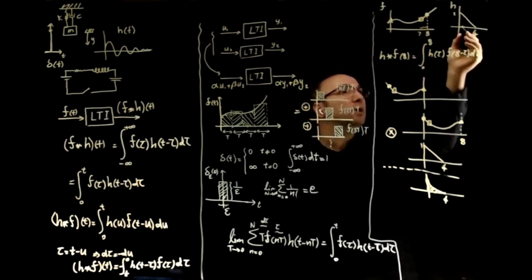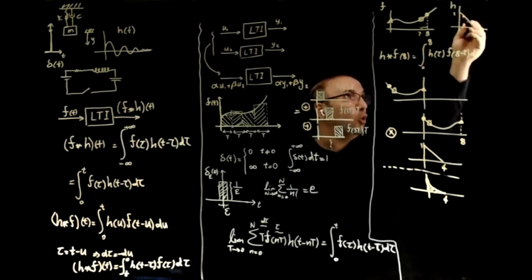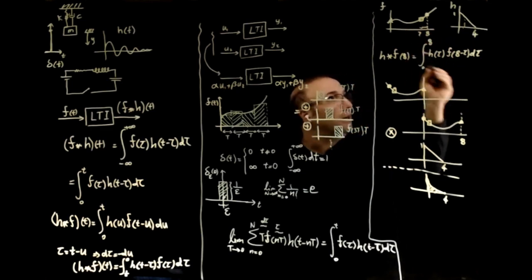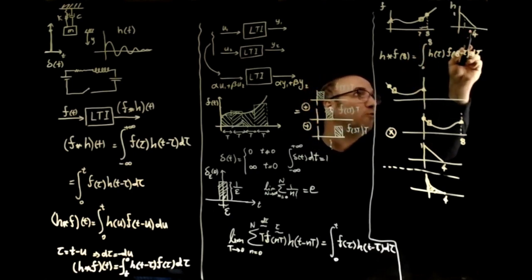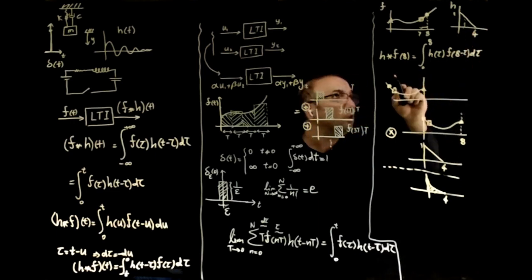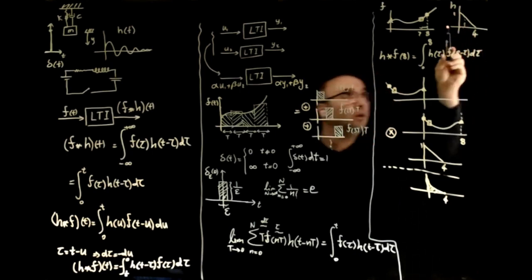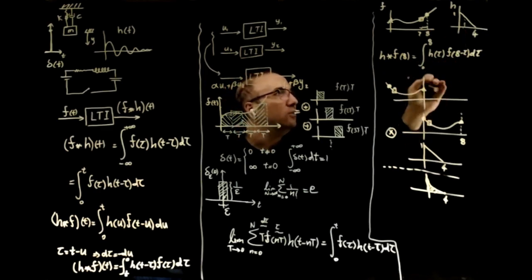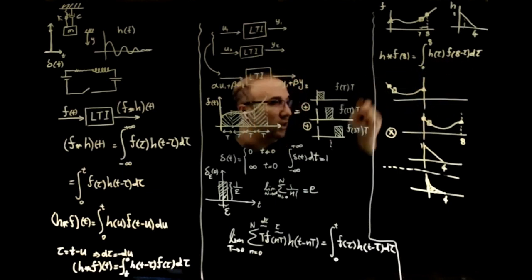So we are here in the impulse response, because the impulse response started 1 second ago. So it is 1 second past in the impulse response. So you see, when we march back in tau here, we march forward in tau for the h. So that's why something that happens at 8 seconds is just at the beginning of that impulse, and something that happens 1 second before is 1 second past. And you see that tau, h minus tau, or t minus tau for the general case.